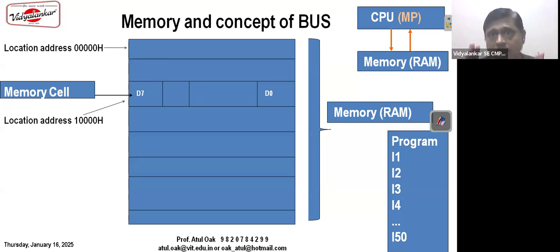Address bus is a group of wires, a metallic conducting path, which carries this information. Observe it, the one which I am referring to by mouse pointer, the address. So all your address locations of memory, you communicate via address bus. Address bus tells which location of RAM, which IO device you want to access. It carries the information of location. It tells the microprocessor where to go. The answer is address bus.